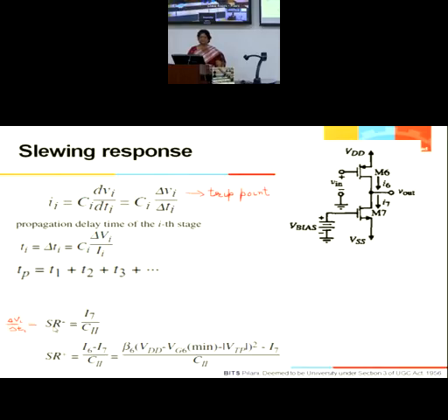So we may have a positive slew rate or a negative slew rate. Positive slew rate, as I said, is because it is charging. This node is charging, it will charge through the current. So when this node voltage is going low, it will have a very heavy VGS. I6 will be very high. So net current going through CL will be I6 minus I7. Charging, output is charging. It's going high, so positive slew rate. Output is going high, positive slew rate. I6 minus I7 by CL.